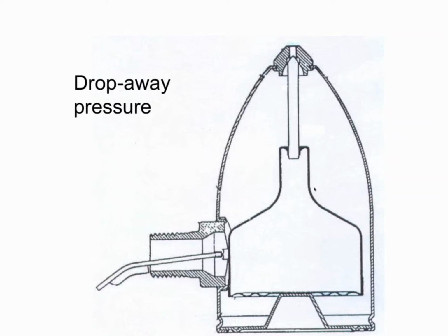The real old antique. Some of y'all have seen them. Some of y'all know what I'm talking about. Some might have no clue of what I'm talking about. But these are the areas you would find this particular vent, or you might find it on a riser pipe, at the top of a riser pipe. On rare occasions, you might even see it on a steam main somewhere or on a return line somewhere. That's rare, but it does exist.